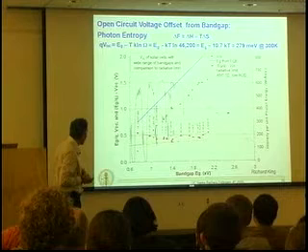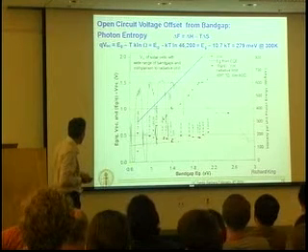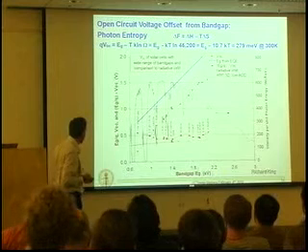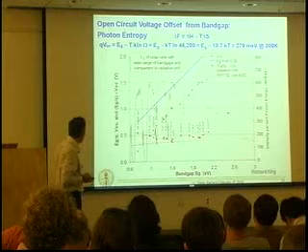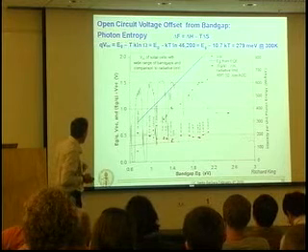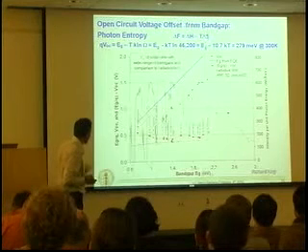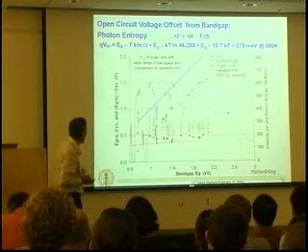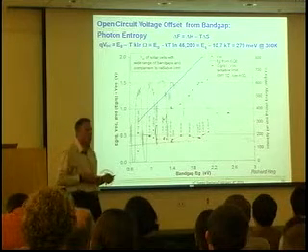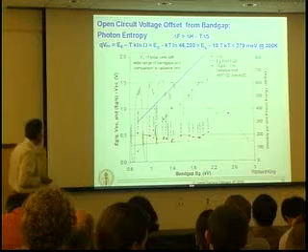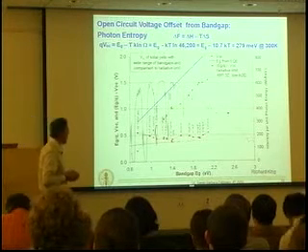So this is a variety of different semiconductor materials looking at the band gap. This is band gap here versus open circuit voltage, and this is the band gap versus band gap. So that's a plot with unity slope here, and this is the offset. And you can see for many semiconductors whose band gaps are between 0.7 and over 2 eV, there's a consistent difference between the band gap energy and the extractable open circuit voltage. It's actually more like about 400 millivolts because there are other non-idealities that come into play.